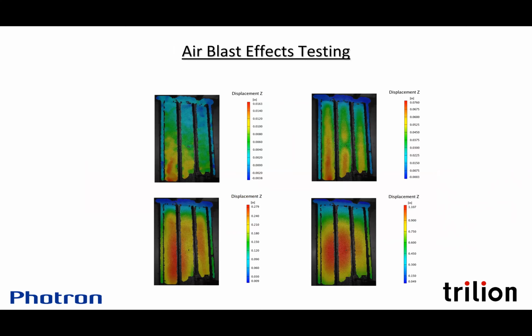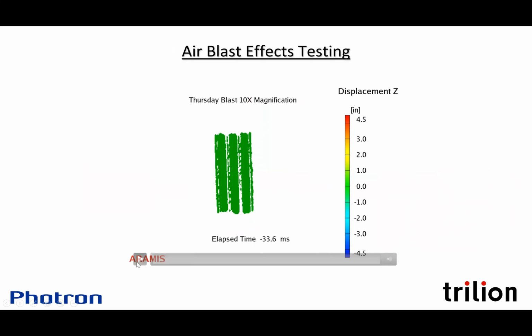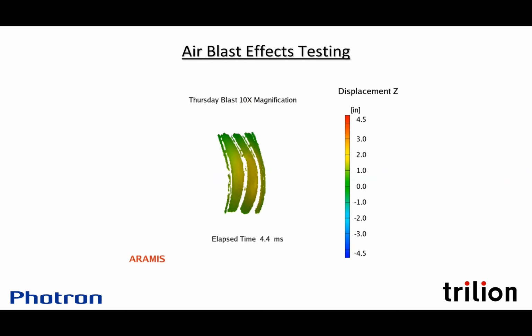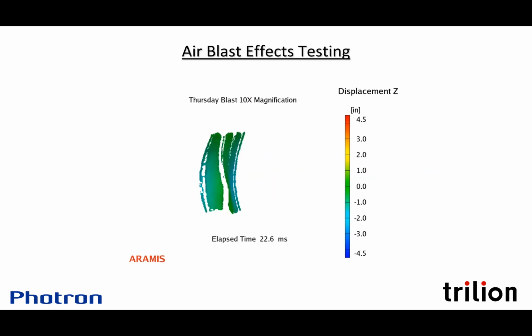This is 4 images from the video showing initial response. Just the bottom left is responding. Then the individual wall boards between the beams are individually moving. They start to link up, and then later the whole side of the building will buckle. This is a magnified view of the 3D displacement. So it's a nice visualization tool just to give a feel for what happened in that test.